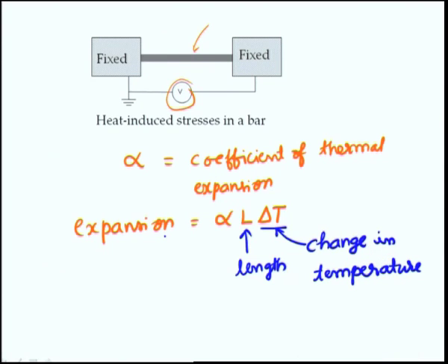We have this expansion. I can write the strain, epsilon, which we had denoted in one of the last lectures also. Epsilon is the strain, in this case due to thermal load, because the heating has taken place and it wants to expand, but it is not allowed to expand. So, a thermal strain will get created with a negative sign.